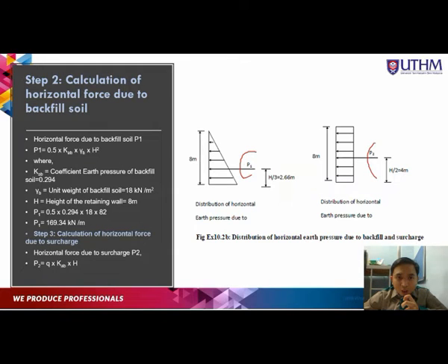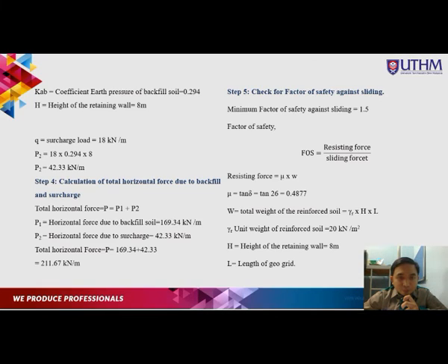P1 is the horizontal force due to backfill soil, and P2 is horizontal force due to surcharge. So this is the formula for the calculation. Next, step 4 is calculation of total horizontal force, which is P1 plus P2.